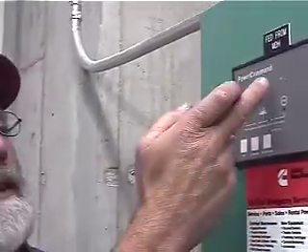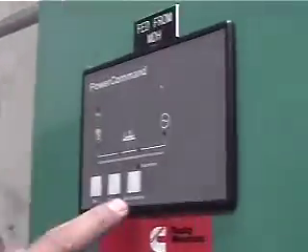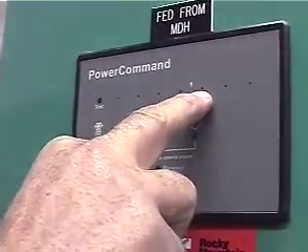You'll use the test button to set the 5 on the left side. You use the override button to set the 3 on the right side. What that does is we can set time delay start, time delay stop, time delay transfer, retransfer, our voltage codes, exercise time, test with load, test without load. There's like 25 different things that we can set inside this control. It'll also be in your manuals.